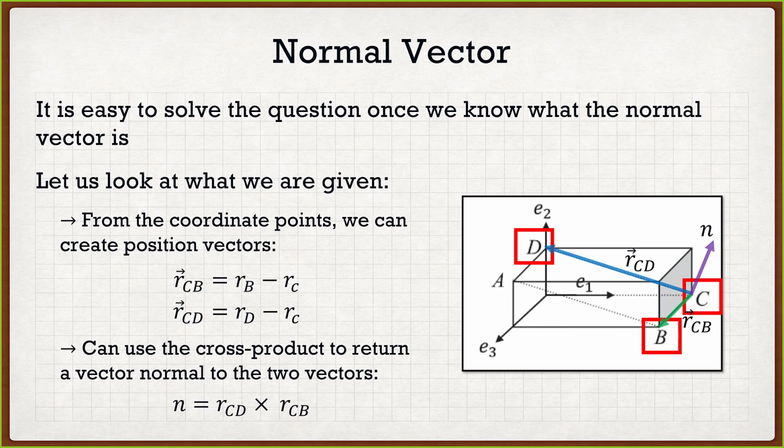Now, a question for you. Does our vector n have to be normalized in order to use those formulas on the previous page? What do you think? I think so. Yes. So that's going to be the trick, and that's the major trick when it comes to the stress formulas: n needs to be normalized. So the first step is to find what n is by crossing the two vectors, and then we normalize it. After that, all we need to do is go to the formulas on the previous slide, and we're good to go. It's basically just plug and chug your way towards the answer.